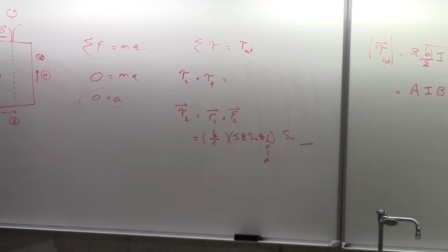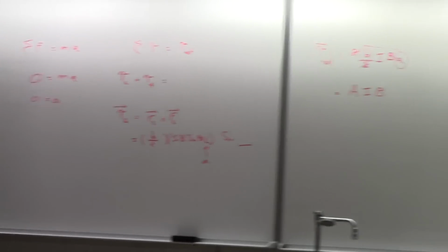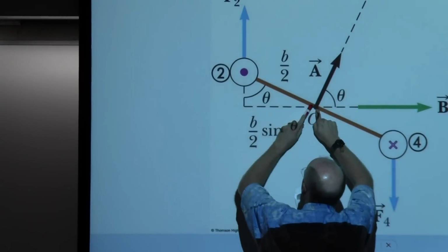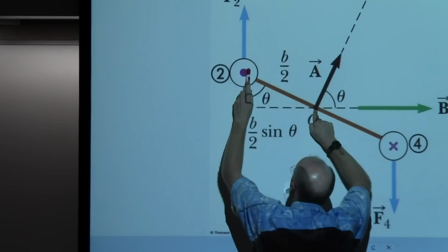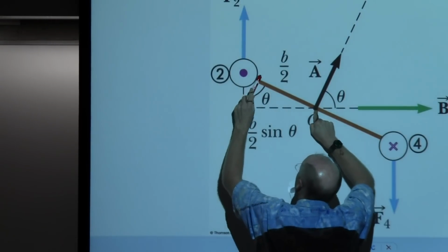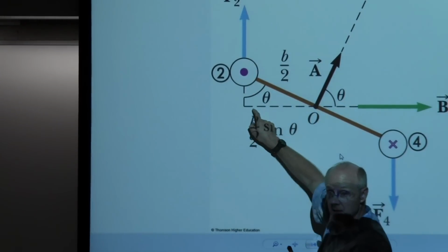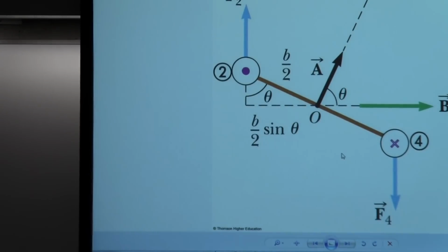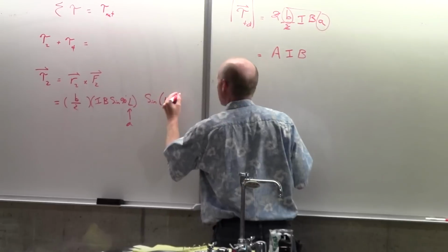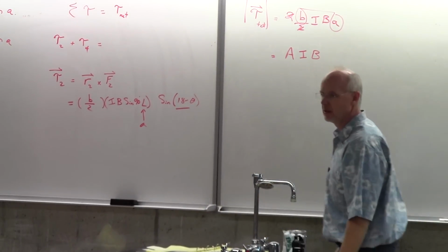What is our definition of a cross product again? Well, I guess it's the angle between r and F. So where's r? Well, I guess from here to here is r, right? And there to there is F. So isn't this the angle between r and F right there? Isn't that 180 degrees minus that theta? And so I would say this is 180 minus theta.